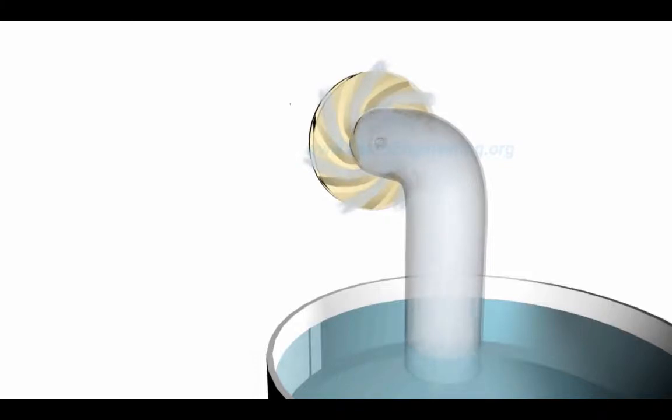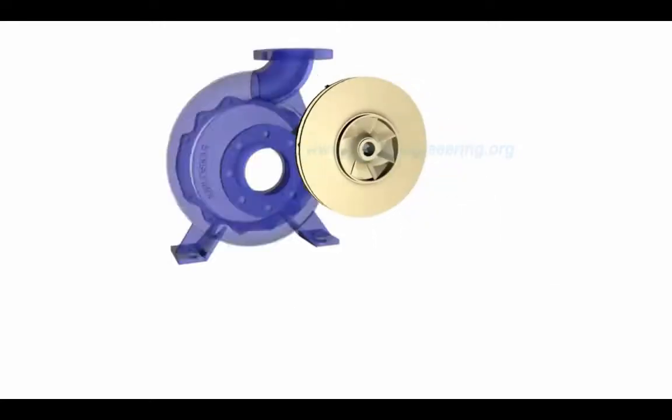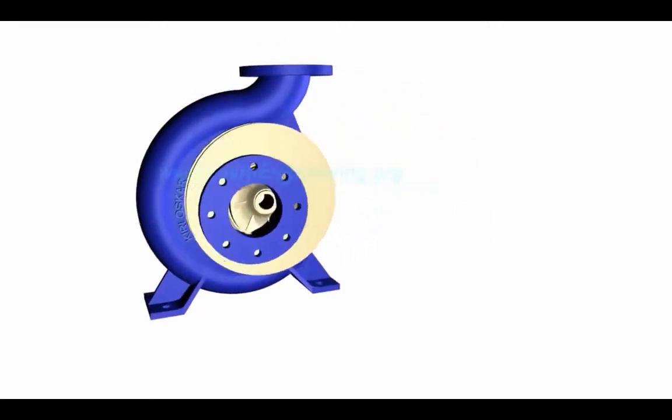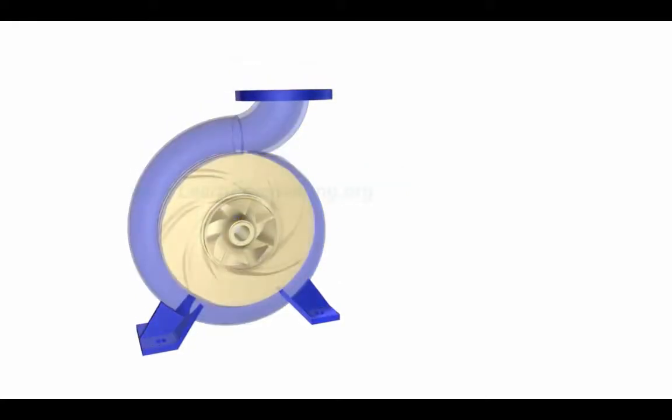This is the reason why priming is important for centrifugal pumps. If no water is present initially, the negative pressure developed by rotating air at eye of impeller will be negligibly small to suck fresh stream of water. Impeller is fitted inside a casing, so the water moving out will be collected inside it and will move in the same direction of rotation of impeller to the discharge nozzle.